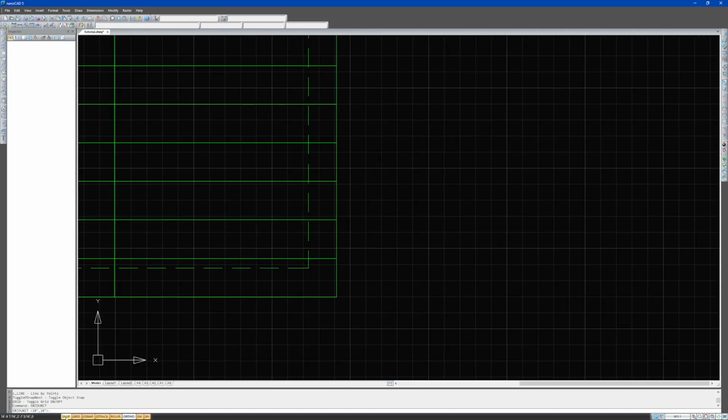which is right here, it goes hand in hand with the grid. Let me show you how. So now when I start a line command, you'll notice that I could pretty much move my cursor anywhere. But if I turn the snap on, it's off by default, and personally I never really turn it on. But if I turn the snap on, notice what happens. Now my cursor is locked into, kind of locks onto those intersections.